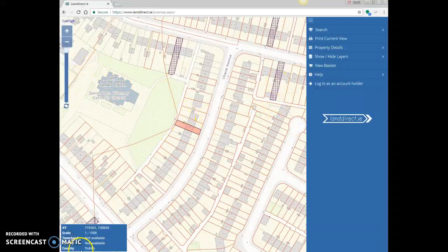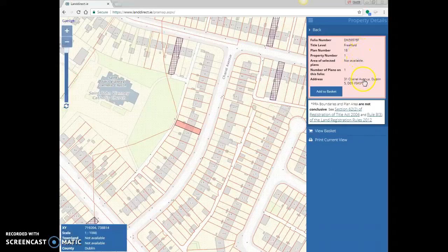Now, what I want to do with the scale bar: previously we had a scale bar on our drawing. This time I'm not going to have a scale bar on my drawing. So this time what I'm going to do is I'm going to use the scale. So when I export it, I'm exporting it as per the scale, and then when I get into AutoCAD, I'm scaling it back up. Okay?